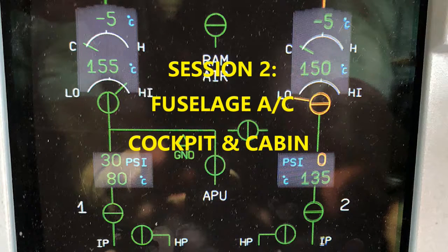The pack controllers in particular are located in the avionics compartment, forward of the nose wheel well, on 95 VU and 96 VU. Okay, you can get through that same area even for the zone controller through the access door 8011.